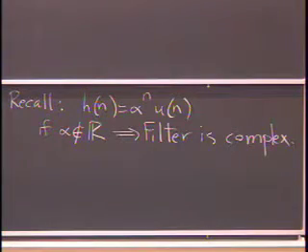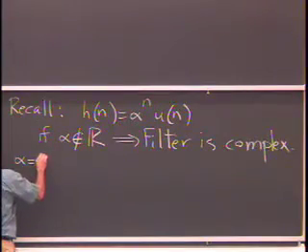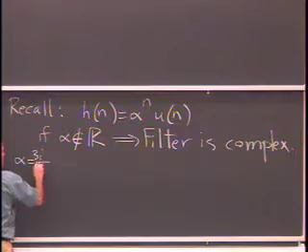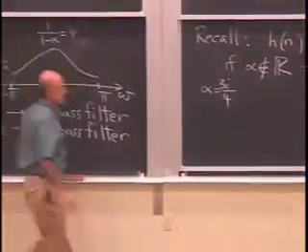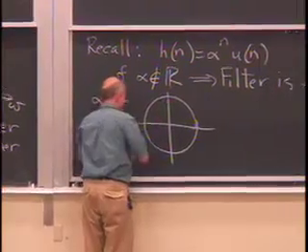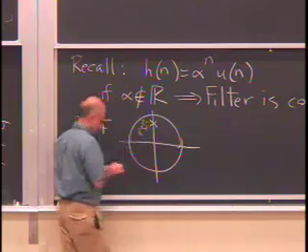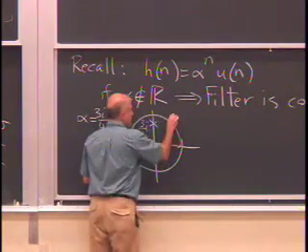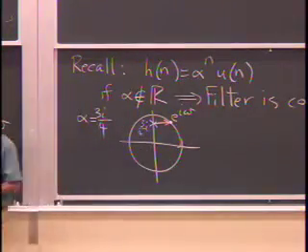So your solution to creating a bandpass filter, let's say that peaks at pi over 2: let's say alpha is 3i over 4. This one was at 3 over 4. Let's put alpha at 3i over 4. On the circle, you'd have an x here, 3/4 i. And your e to the i omega would be on the unit circle. Your red vector would be from the x to the e to the i omega point.